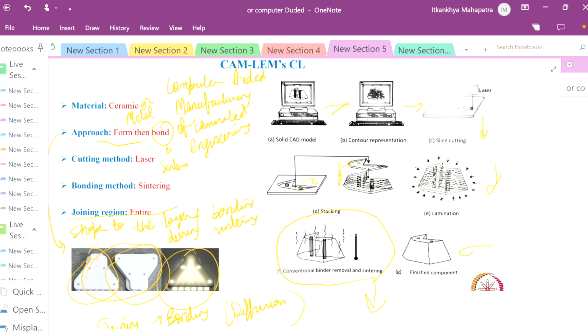During that phase, a lot of shrinkage will occur if you are using a very complex geometry and the thickness of the wall is very thin. If you are trying to print the thin wall, it will be very difficult because it will try to buckle at some point.